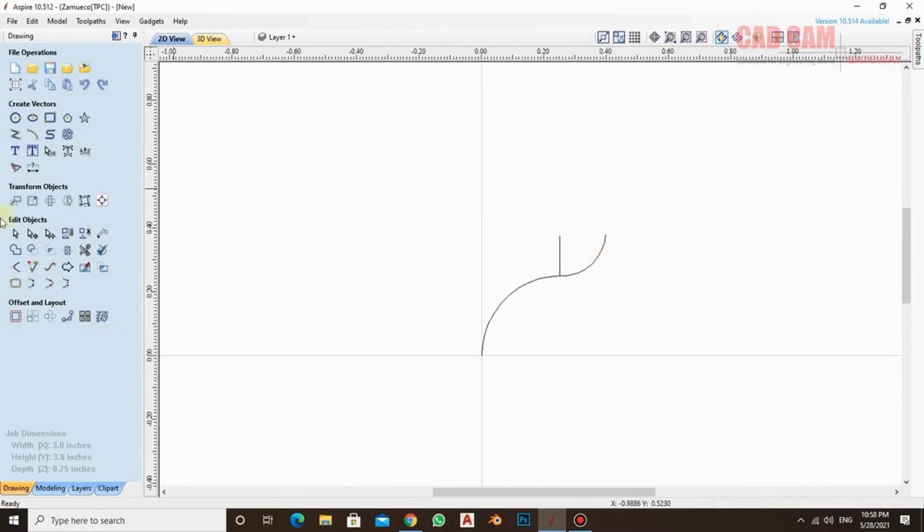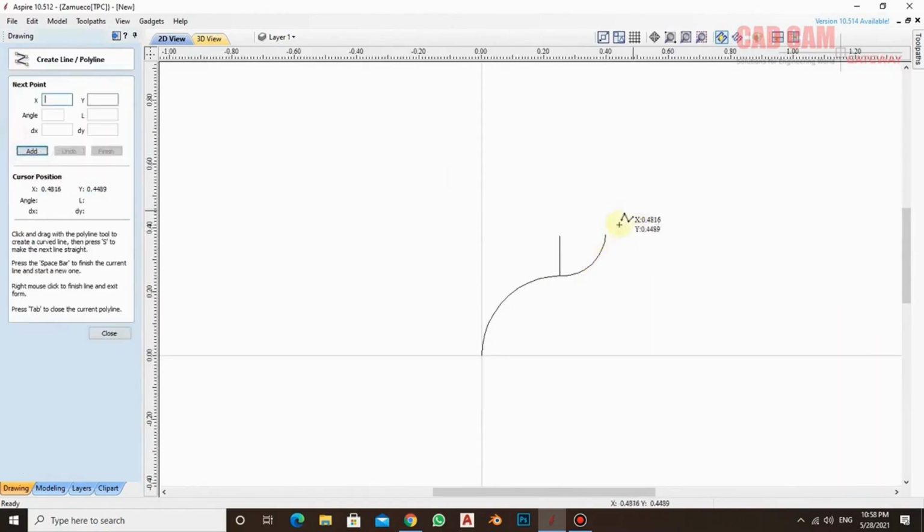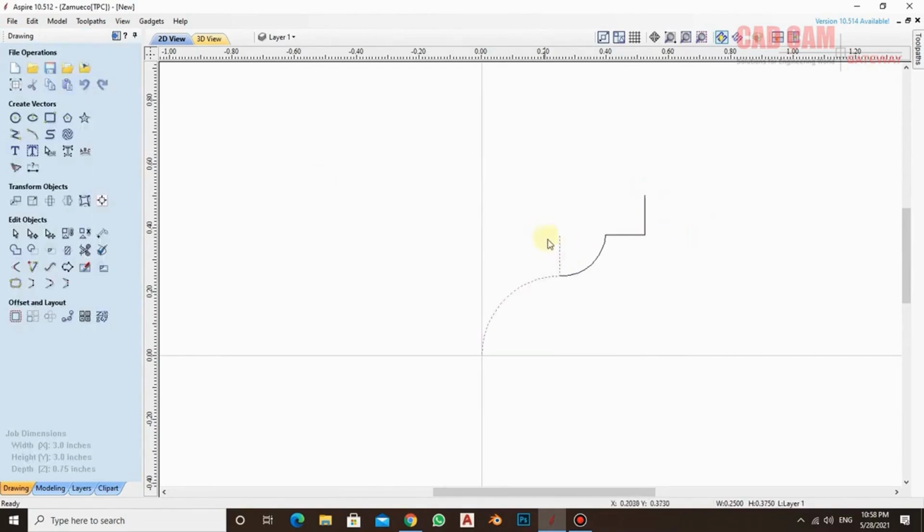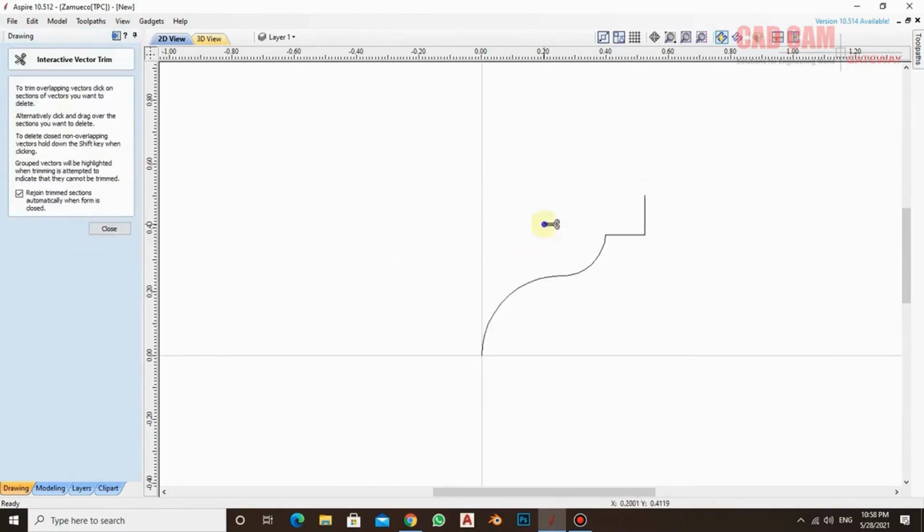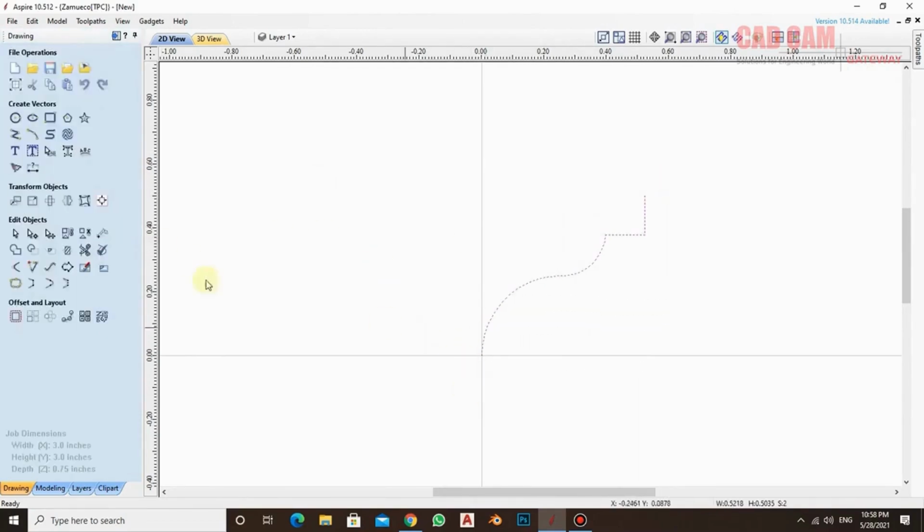After that, from here I set this line in dynamic X to 0.125. Here it is. And then I set it 0.125 upward. So now I will trim this line from here. See, as soon as I trim this line and join this object, after joining, close it. So now this is the profile. Now look at this. When the border is created from this, it will be formed in this way. Meaning the border will come here.